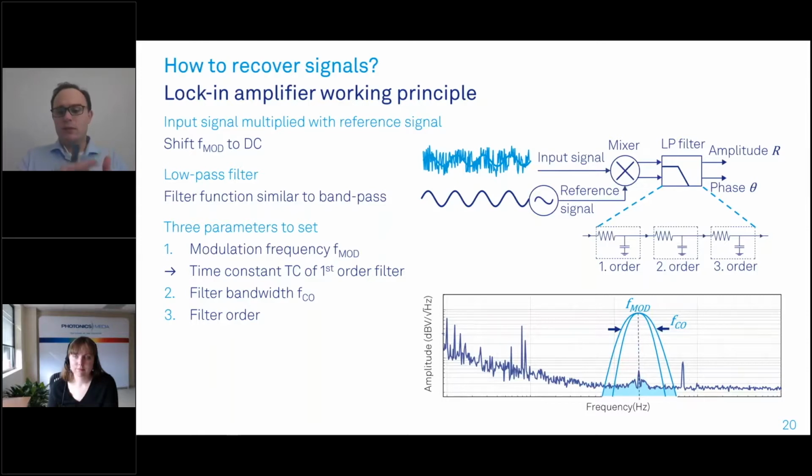You have to put the repetition frequency as well as the position and the width of your boxcar window into the signal detection process. But precisely due to this additional information, you can benefit afterwards. So I would always suggest start with a lock-in, and if you want to go for ultimate performance, maybe call us, double check, and we can assess if a boxcar is a better choice for you.